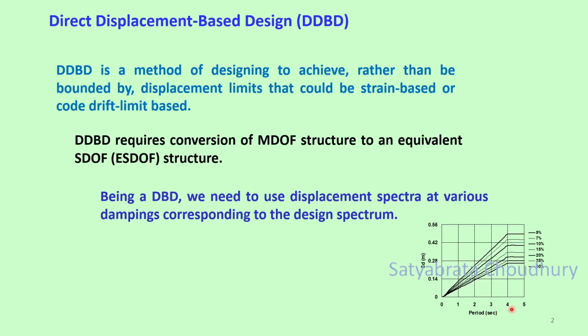It is a reverse process of that given in the code as force-based design. In force-based design, from the time period you get the force, the acceleration value Sa by g. Here, from the spectral displacement you get the time period.